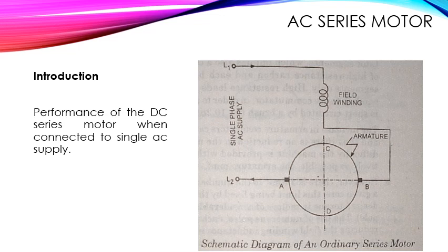So as a consequence, both the windings act as open circuited primaries of transformers, and therefore each winding has large reactance. And this results in small current and abnormal voltage drop, and that reduces the output and power factor to such low values as to make the motor impractical.